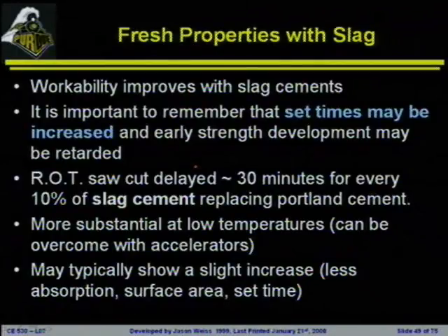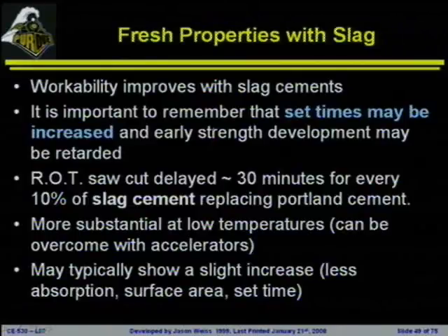Yeah, that water will just be used to quench the material, and then they'll go on and process it from there. They'll have to grind it. The main thing is once it gets into a fine powder, you don't want it to be wet because it's going to be just like a Portland cement. So at that stage, it doesn't matter. Right. The water will make a difference. Right, because you're going to create a whole lot more surface area once you start grinding it up.